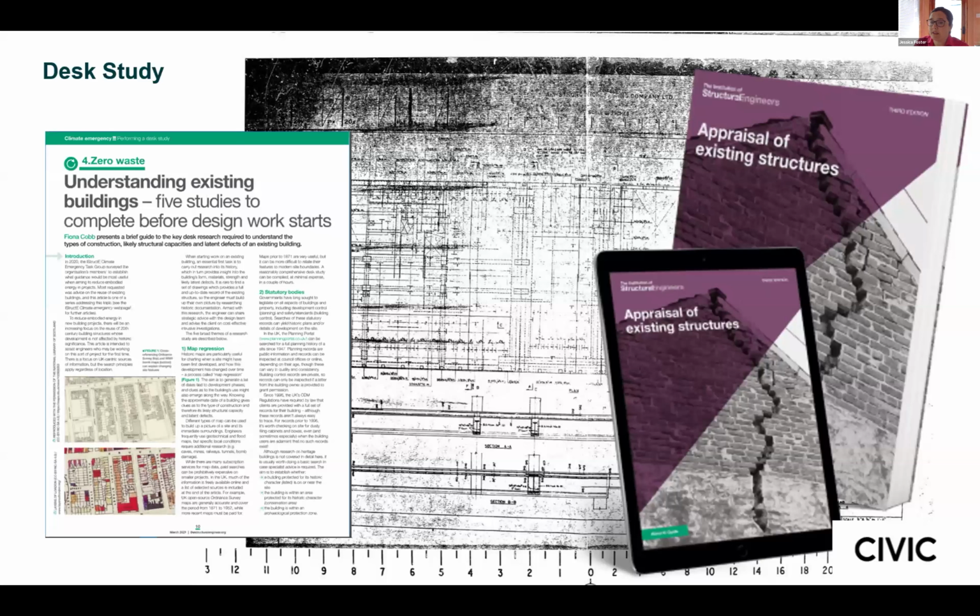You've got to bear in mind that historic drawings are not as-built information, and it's typical for older buildings to have undergone multiple lives and fit outs, which can have structural impacts. So removal of columns, removal of load-bearing masonry walls, additional removal of windows, new floor openings to facilitate lifts, staircases, double height spaces. These are really, really common, and they will not be recorded on the original drawing. So it's really important to verify any historic information you have on site.